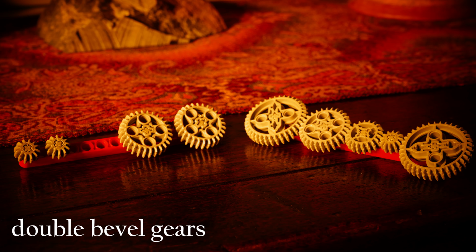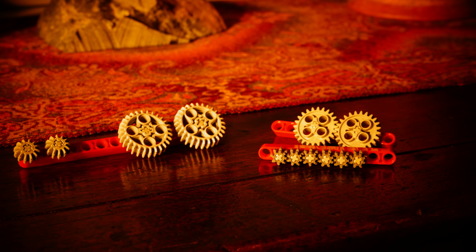Unlike LEGO spur gears, LEGO double bevel gears cannot be paired with gears of the same diameter. This is because their number of teeth is not divisible by 8. This social distancing is observed on the left, with 2 12-tooth gears unable to touch, and 2 28-tooth gears unable to touch. To the right, the entire family of double bevel gears is demonstrated, including the 12, 20, 28, and 36-tooth gears. Again, for reference, spur gears can touch themselves, whereas double bevel gears cannot. This can make the design of double bevel gear trains less straightforward, and in part spurred my interest in designing software to overcome this challenge.